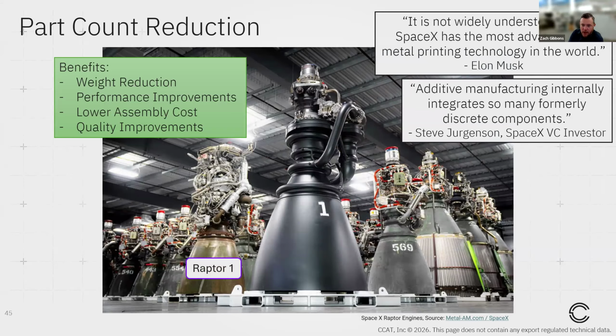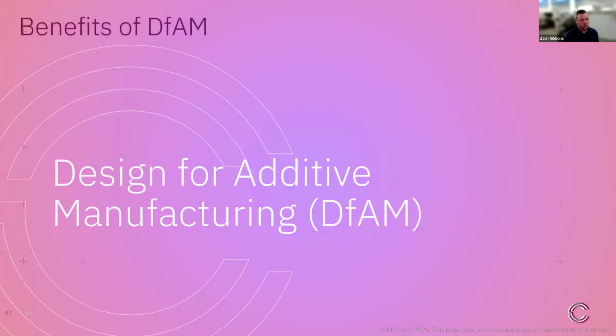And so we can see from Raptor 1 to Raptor 2 to Raptor 3, it almost looks like the engines are getting simpler. What happened was they went to internal features to redesign their parts, so their parts are effectively pulling double duty. That nozzle in Raptor 3 has a lot of internal conforming flow paths through the actual bell of the nozzle, and because of the way they redesigned these parts, they have since been able to remove any external hardware related to rocket cooling.